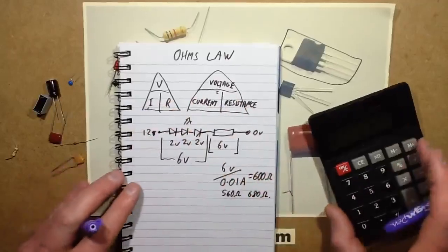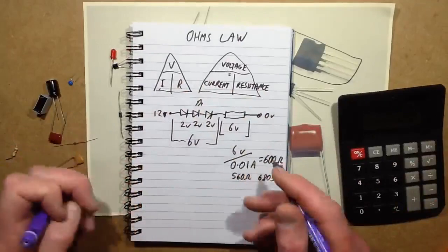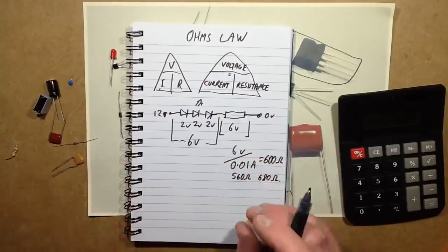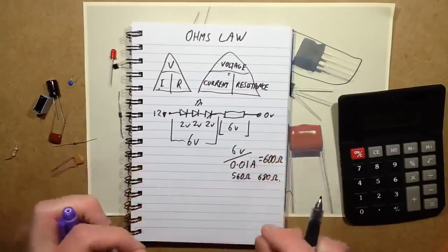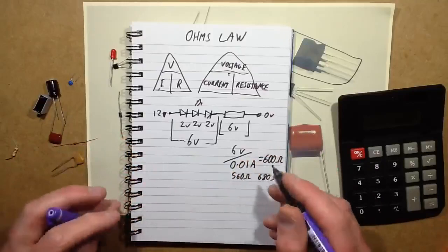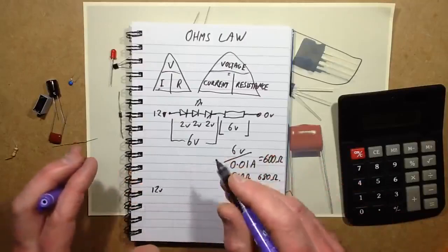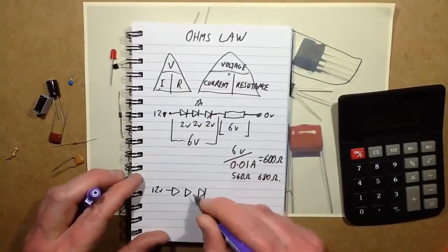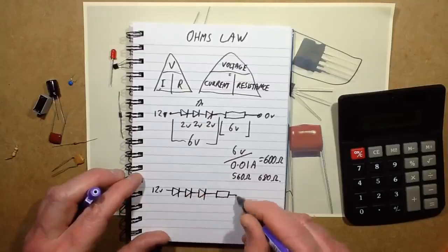And the other way this formula can be used is if you are trying to measure how much current's flowing through some existing LEDs, say for instance you're measuring some LED tape, and you might find that putting an ammeter in series with it actually skews the reading a bit, because the voltage drop across the resistor in series with LEDs is so low. So say for instance you've got a 12 volt supply and it's feeding more LEDs, but you don't know the voltage across the LEDs and you don't know the current through them, but there's a resistor and you do know the value of the resistor.